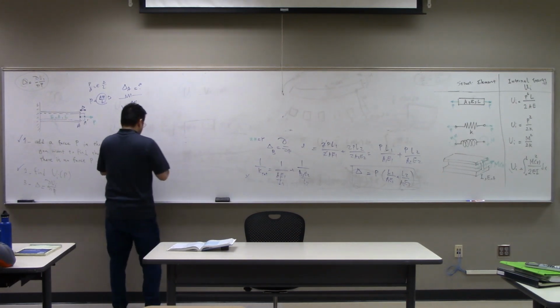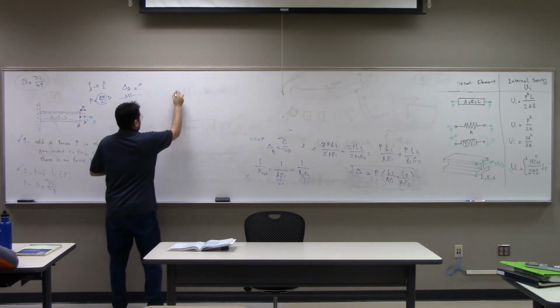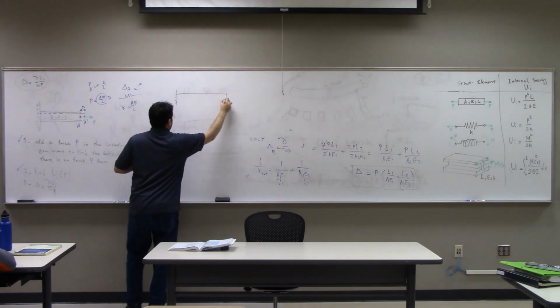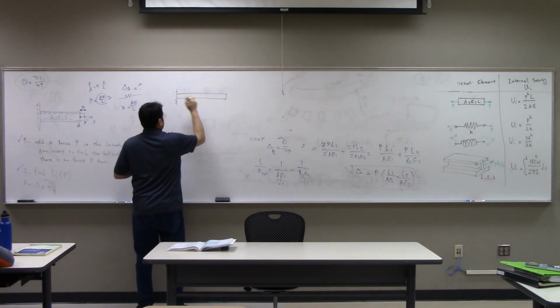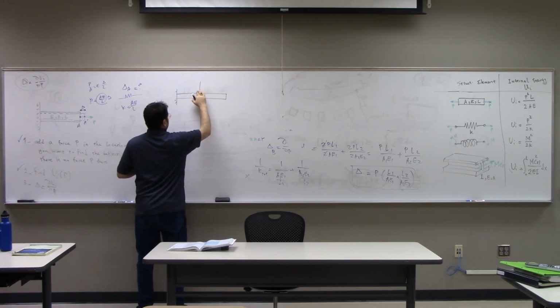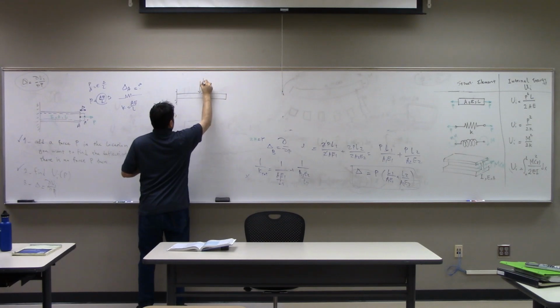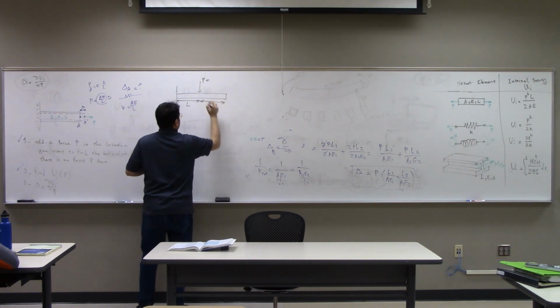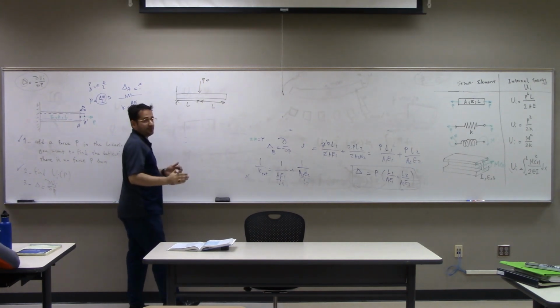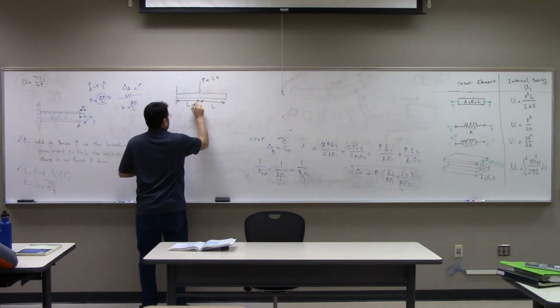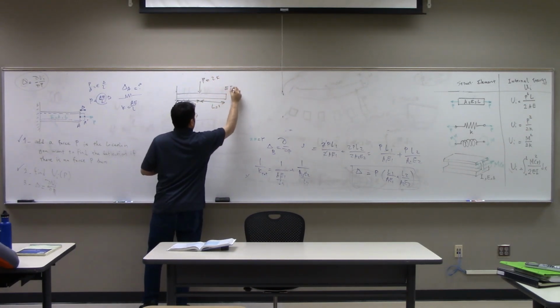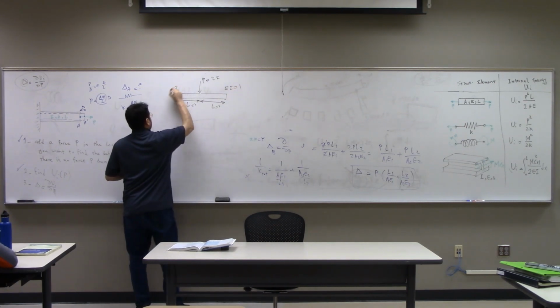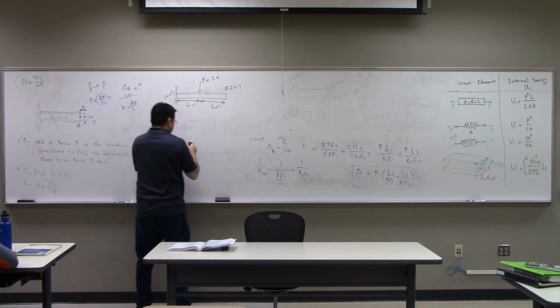So you have the beam and this force applied to here, let's make it P, and from here to here L, from here to here L. Let's say values are, we can solve it parametrically, or we can use 2K here, 1 meter, EI is equal to also 1. And this is what? Find the deflection at point C.